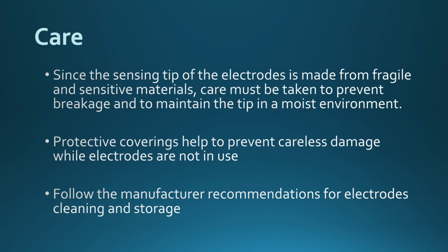Now, regarding the electrodes that we mentioned, special care should be applied to these electrodes because they are made from fragile and sensitive material. Care must be taken to prevent breakage and to maintain the tip in a moist environment. So some manufacturers provide a protective covering for these electrodes. And it's very important to follow the manufacturer's instructions for handling, storage, and of course the cleaning of these electrodes.